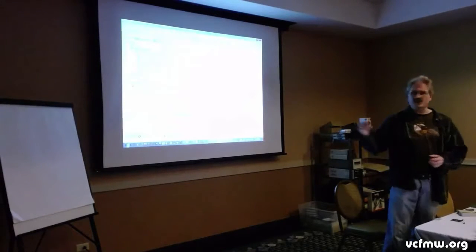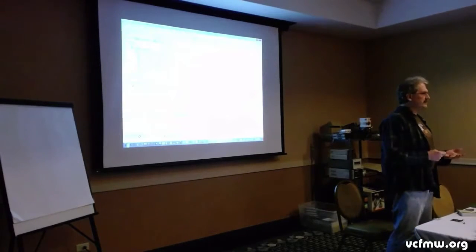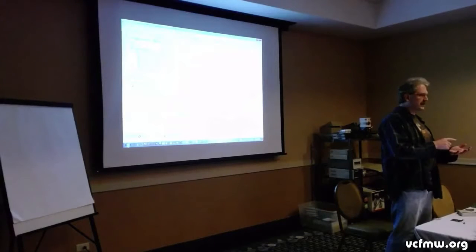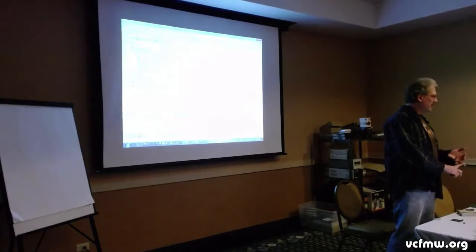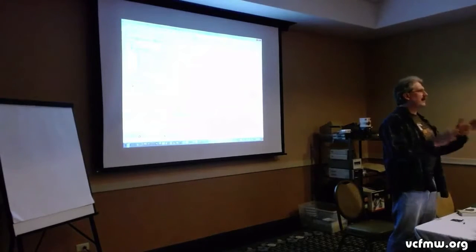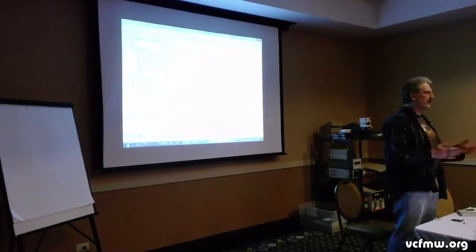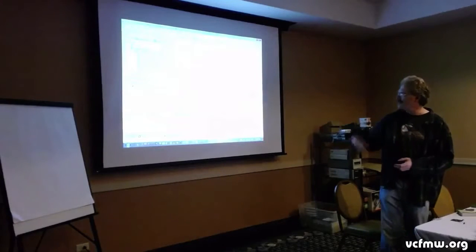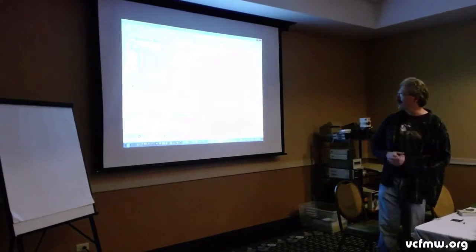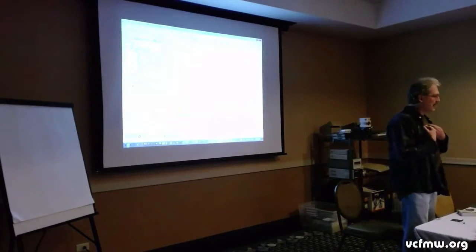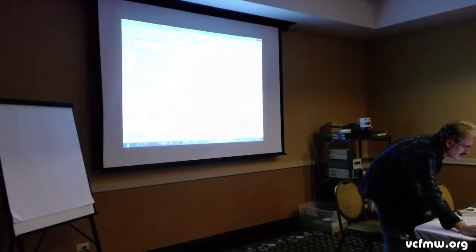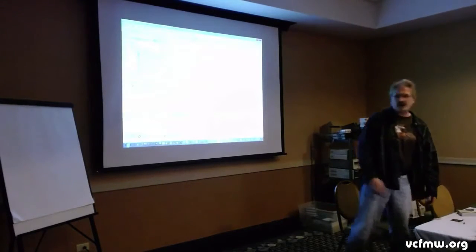Those kinds of things. So sometimes you need to be able to set registers to say, hey, I want this particular I/O chip to be in an address space at this byte or at this area of memory, as opposed to at the bottom of memory all the time. So one of the things you can do in this case is create registers. Now this particular thing says register, which is something I've defined, and if I click on it here, it will load up another piece of code, which you could load inline.